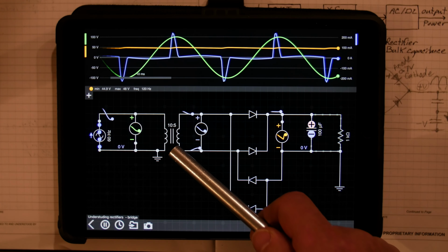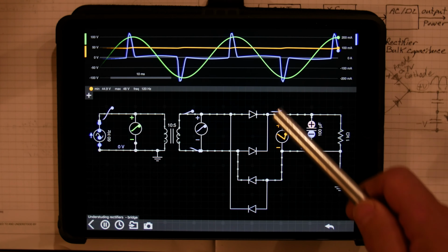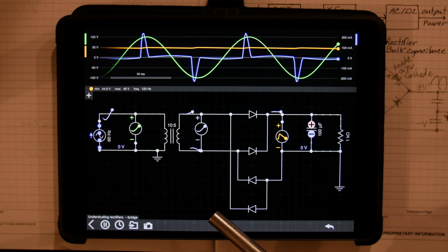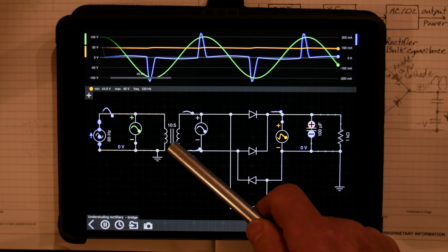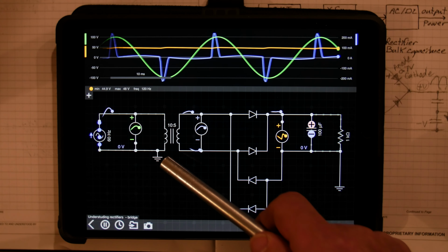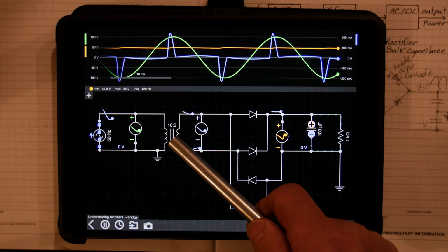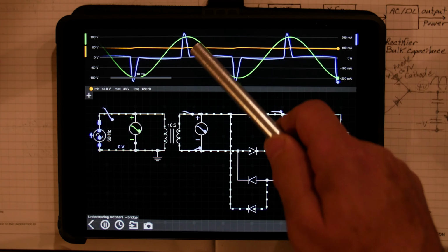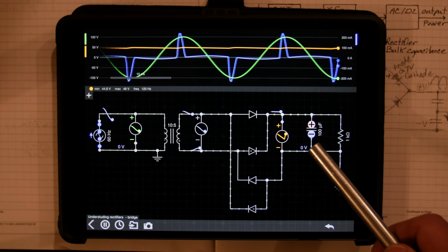it's not putting out RMS sinusoidal current, it's putting out these big pulse currents. So if the transformer is designed for a lower steady state current, then there's going to be some losses in the transformer when it goes to these high peaks. These are all considerations.